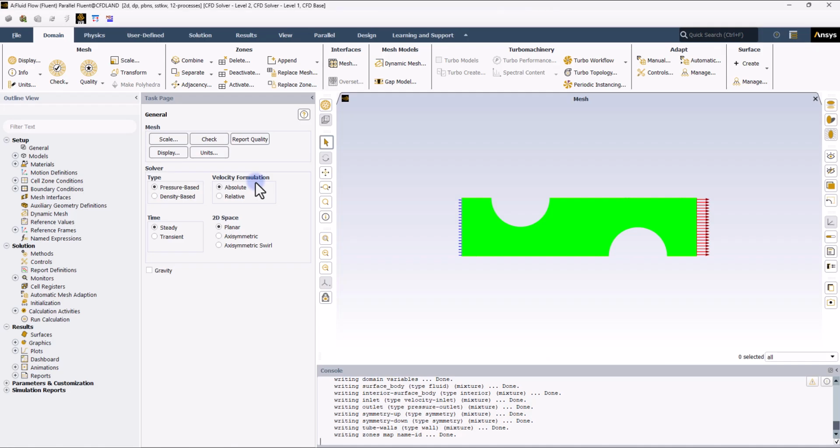Very well. Finally, it's time for the solver settings. On top, the general settings, which include the general assumptions of our governing equations. First of all, we're going to employ the pressure-based solver, which means that the density changes inside the governing equations will be ignored, and this is used whenever we're dealing with incompressible fluids. In our current simulation, we're going to have the volatile liquid as the working fluid. This is why the pressure-based solver will work.